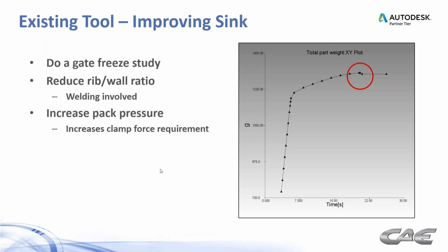Increasing pack pressure, that's another process fix. Problem with that is now we're making ourselves more susceptible to the clamp force requirement.